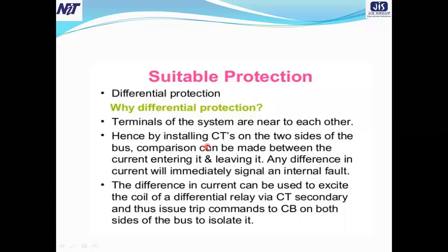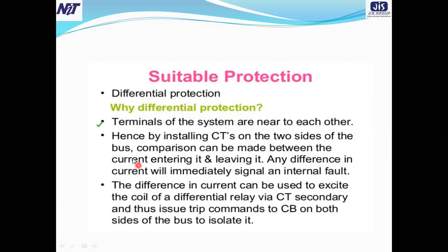Number one, terminals of the system are near to each other. So for that reason, differential protection is required. Terminals of the system are near to each other. Number two, hence, by installing CTs, current transformers, on the two sides of the bus, a comparison can be made between the current entering it and leaving it.